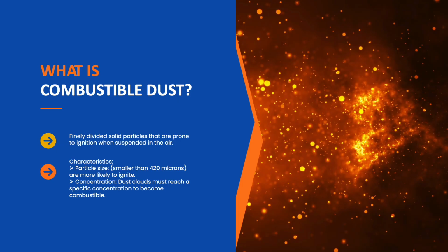On the other hand, you may have something that's not highly explosible generally, but if you're doing a lot of sanding of wood and so forth, you may be creating very small particle sizes and the concentrations that will allow that under certain conditions to catch on fire and explode. So that's basically the idea for what is combustible dust. Next slide, Andy.